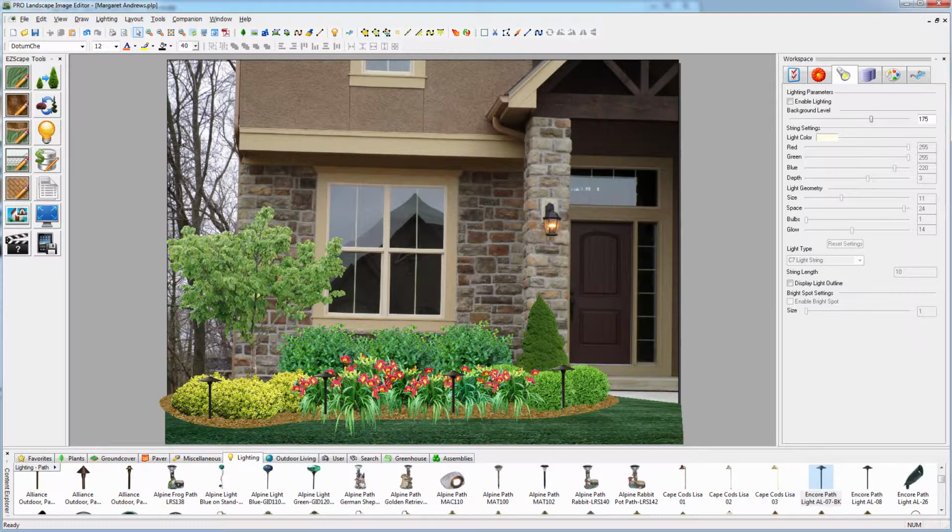Let's come back here to the daytime, and let's go ahead and uplight the area of the stone back behind the plants, and then behind this tree as well. So we'll choose our light polygon tool, and we'll just define this light area that we want. So we'll drag up here. Green dots where we're clicking, it's quite simple. Click a few times. Now this white dot is the light source, meaning the brightest point. So if we were down lighting, from the soffit, we would simply drag that up, but in this case we're up lighting, so we'll drag that down, and we'll see right here that's our defined light.